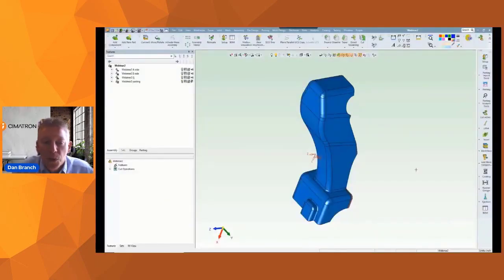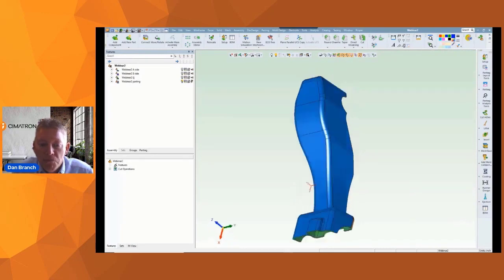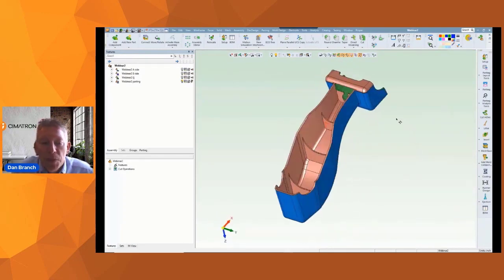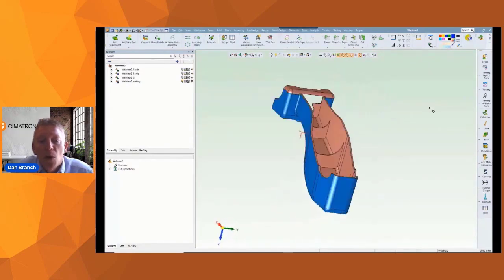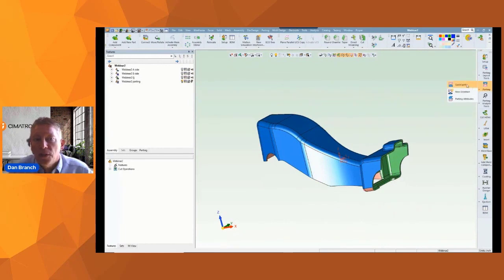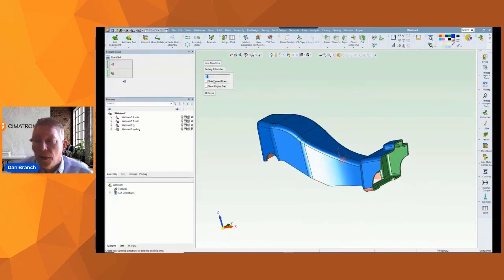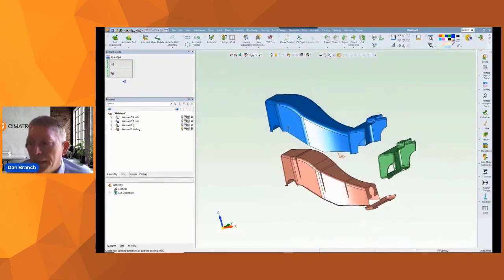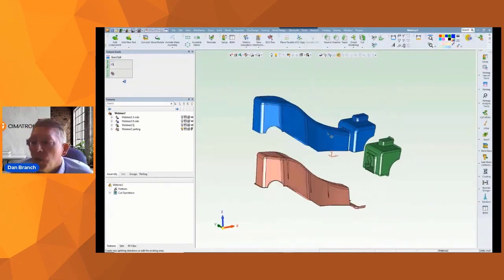Like in the first webinar of this series, let's start by looking at a plastic part to be molded. This time it's a bit of a cover with some deeper walls and features. Our quick split function has already helped me define the main direction of draw here. And it also singled out these surfaces in green as an area that has to be pulled over to the side.